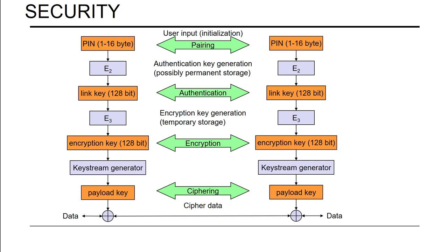From the security point of view, the L2CAP layer provides security with respect to the PIN, and the PIN is nothing but the personal identification number. The personal identification number goes from the sender to the receiver. For example, I have a personal data assistant and a mobile phone. I'm going to share information between the mobile phone and the personal data assistant using Bluetooth. The step of sharing the information takes place. First, pairing of the devices takes place.